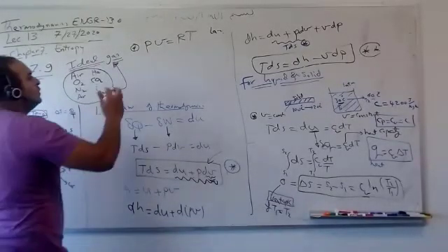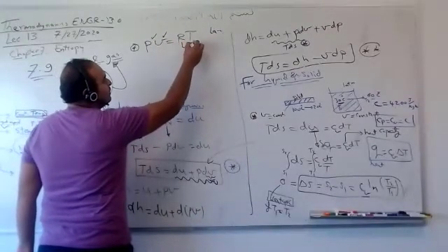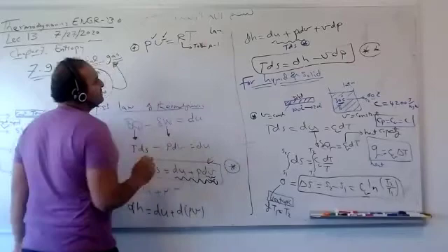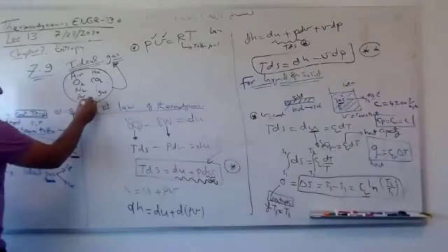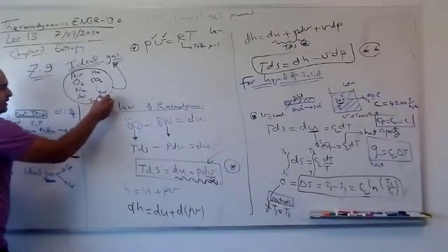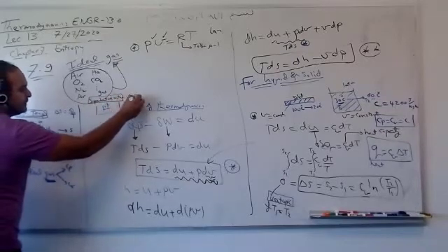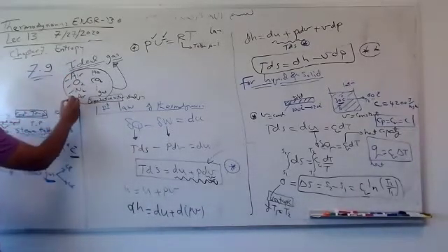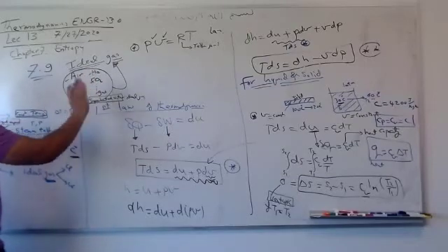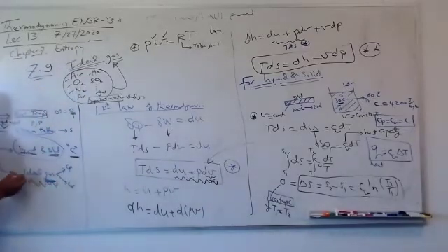The ideal gas law is always correct for any ideal gas. It means if you have two independent intensive properties, you can get the third. R comes from table A1 for this gas. Let's say vapor of air, oxygen, even superheated water. But in this case, I need to say this is an ideal gas. I need to say superheated water vapor is an ideal gas. But otherwise, like air, oxygen, nitrogen, carbon dioxide, helium, any gas I say in the exam, you can use ideal gas equations without even thinking.